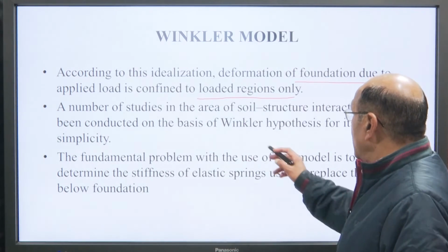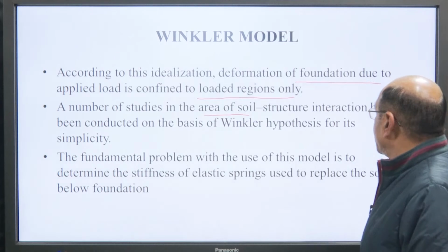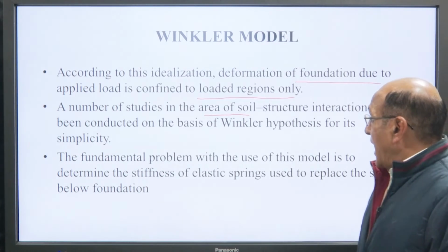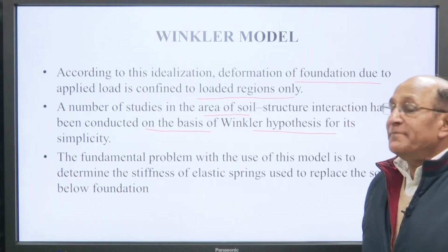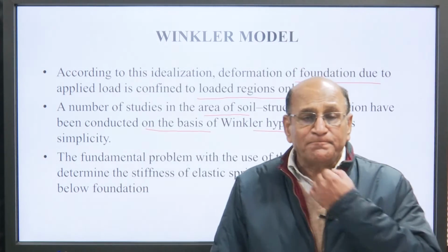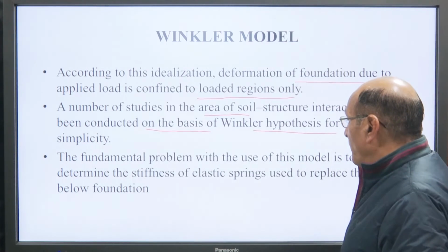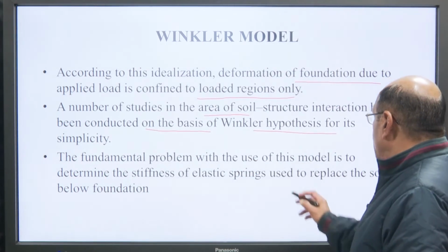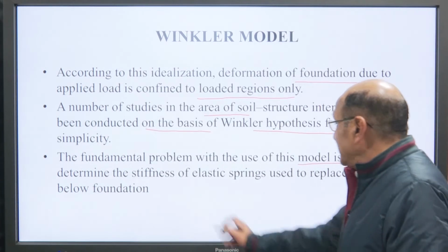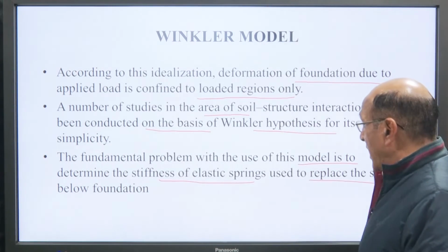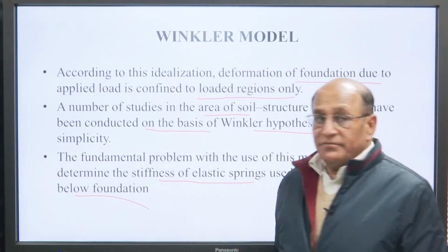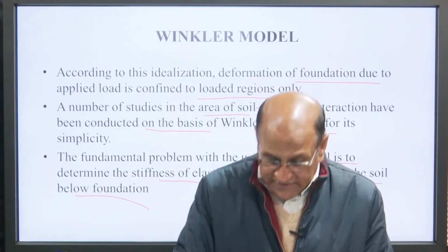A number of studies in the area of soil structure interaction have been conducted on the basis of the Winkler hypothesis for its simplicity, because it is very simple. The fundamental problem with the use of this model is to determine the stiffness of the elastic spring used to replace the soil below the foundation.